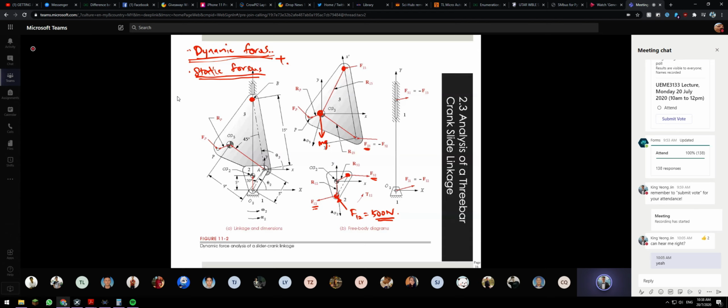That's why, when you are selecting a bearing, if you look at the catalog, they always have the static load and the dynamic load. That's why you cannot put static mg into your calculation, otherwise your dynamic load will be very high. So we only look at the dynamic load, taking out this component.